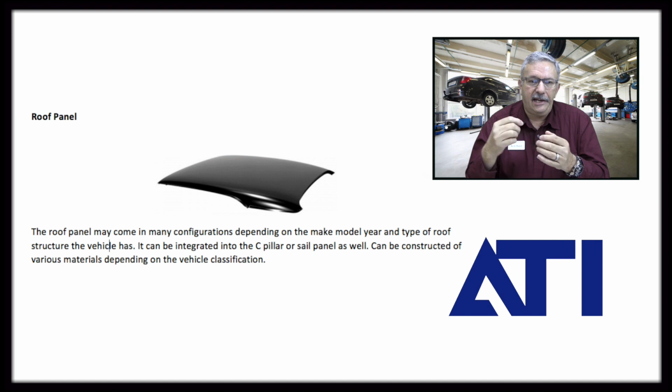Also, there is a secondary welding process. It's called silicon bronze, where I would join the panels together. That's another thing that we have to consider because it is a different type of welding than we would use in our traditional, let's say, squeeze resistance type spot welding. So these are some other areas in the roof panel that, again, we just have to be knowledgeable about the material that we're working with.